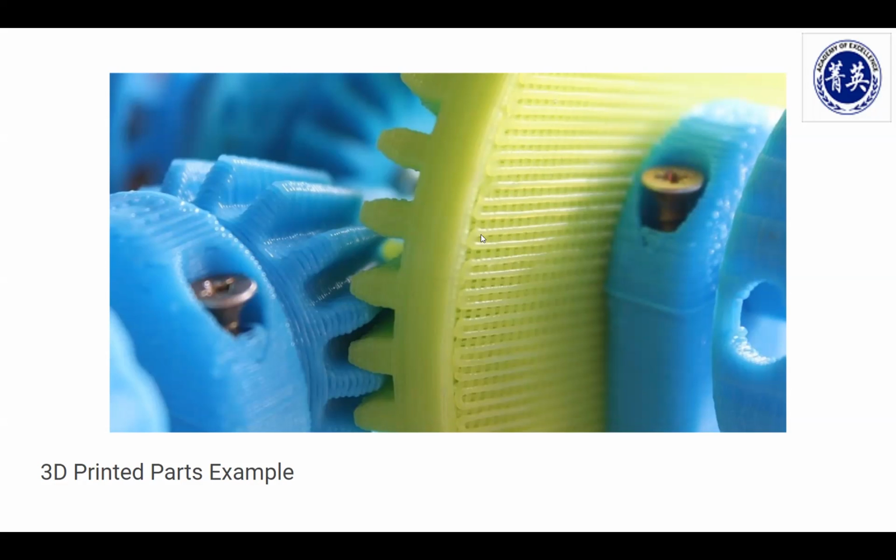So to design something to be 3D printed, sometimes you have to increase the tolerance of the parts, meaning make the gap a little bigger, right? The mating surfaces. If the actual metal or plastic part is made out of real material or by injection molding, the tolerances could be a little bit tighter than what 3D printed material can be. You can see the gap in there, two gears here, the blue gear and the green gear. The gap is actually rather significant because for the 3D printed material to work, it has to be big, because the surfaces are not clean.